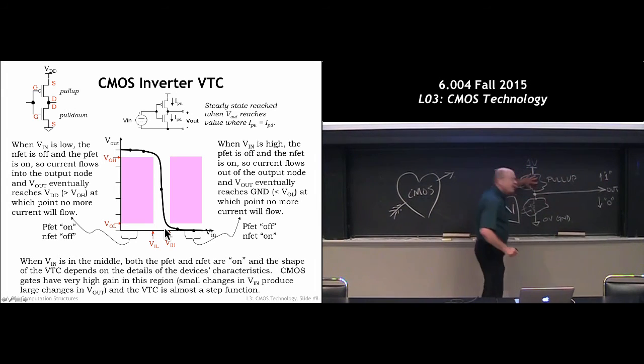Voltage, little switch networks, you can think of them as switch networks, that control whether the output node is connected to the power supply or to ground. So that determines the output node's value. Those switches are controlled by the voltages on the input nodes to our logic gate. And we're going to arrange it so that these two switch networks are complementary. In other words, we design the switch network so that if there's supposed to be a pull-up path, there's not a pull-down path, and vice versa. So if one switching network is on, the other switching network is off. That's what it means to be complementary.